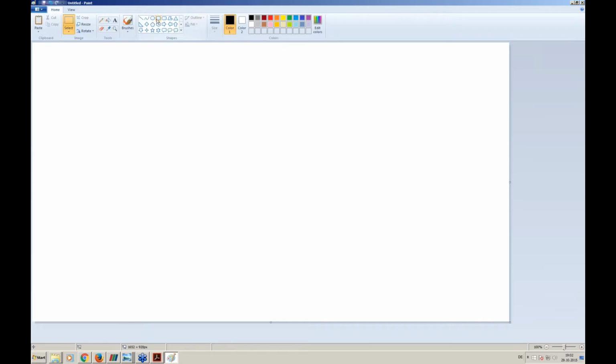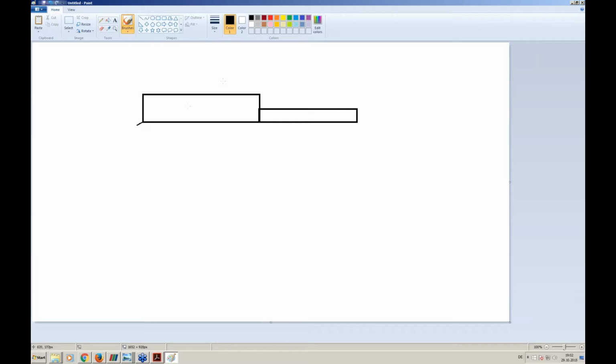I think you all can remember when we did the simulation of the drone arm. It was, again, a very simplified sketch, where we fixed the drone here, in order that it's not moving when we're acting the force. If we wouldn't have this boundary condition for fixation, the drone would just fly, because there is this old physical law that force is mass multiplied with acceleration.